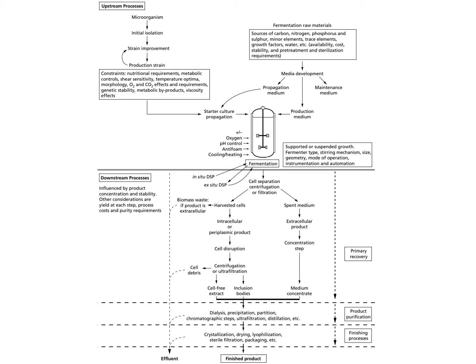And operation like maintaining the oxygen, DO level, pH, antifoam, and everything. Okay, this is not done by you. That is done by the software, because most of the fermenters or bioreactors are fully automated. Once you feed the components, what are the components you need? That is dissolved oxygen, pH, agitation, aeration, and everything. Automatically, that will control. So this is very simple when compared to the downstream process.